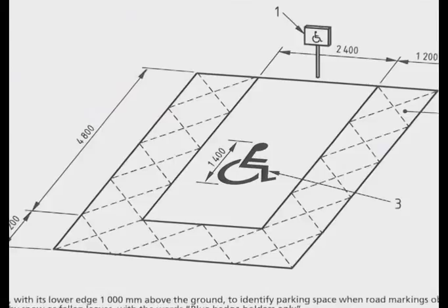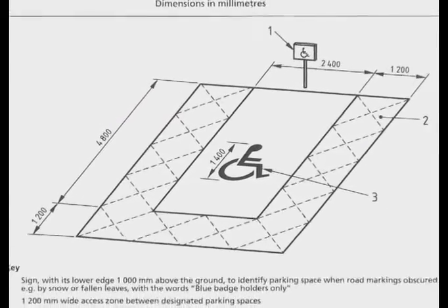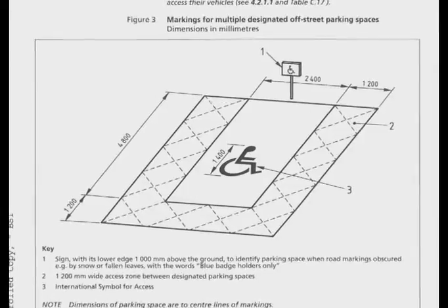Yeah. Let's move on to car parking, something dear to everyone's heart. The provision has been revised upwards for some purpose groups, hasn't it? And it's not just more bays, it's bigger bays, isn't it? There are provisions for larger bays, and also the requirement for bays that can be adapted to accessible bays in the future. Wherever space is available as well, there is a provision for bays for people who use hoists or ramps out of their vehicles. And for that, they need that extra little bit of space.